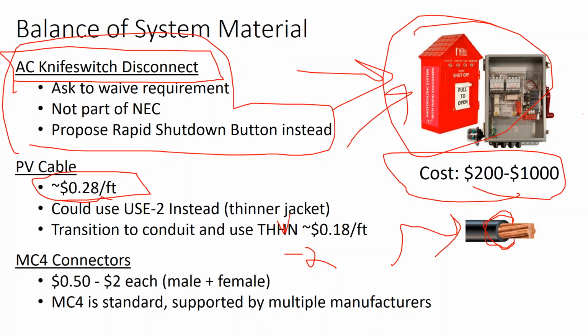I recommend when you go into that conduit and you're inside the building for your home run back to the inverter, not staying in solar cable, but transitioning into THWN2. And the reason is not necessarily because the solar cable isn't good. The solar cable is more robust. It's not necessarily to save money because THWN2 might cost 18 cents a foot. The solar cable costs a dime a foot more, but we're only talking about maybe 100 feet of cable or up to 500 feet, 10 to 50 bucks. That's not worth the complication of dealing with multiple kinds of wire on the job site.